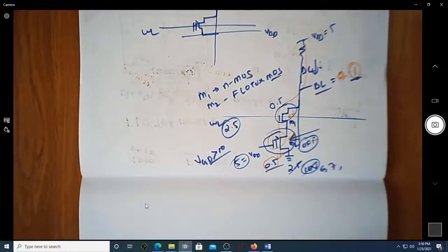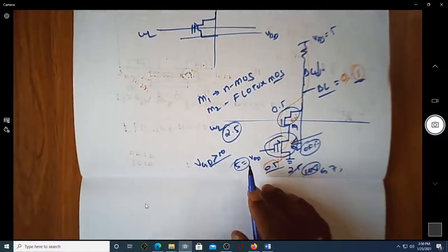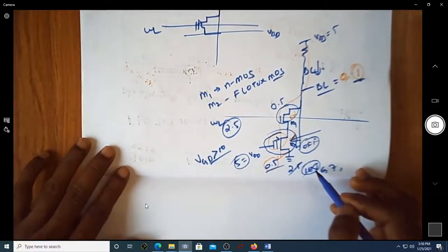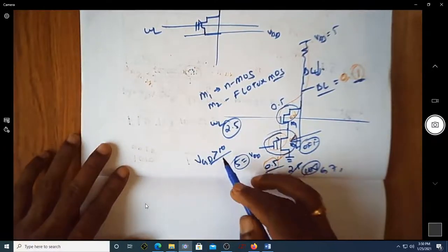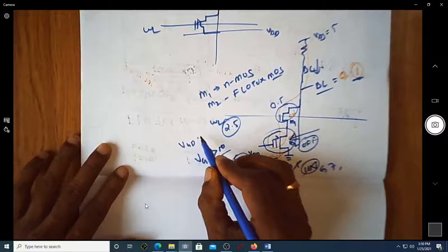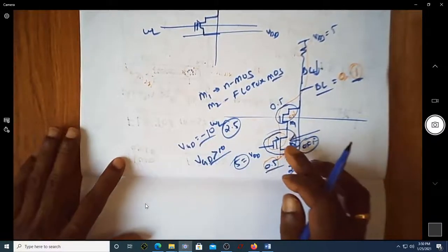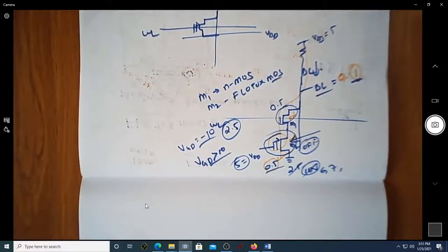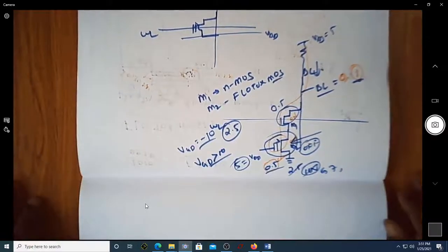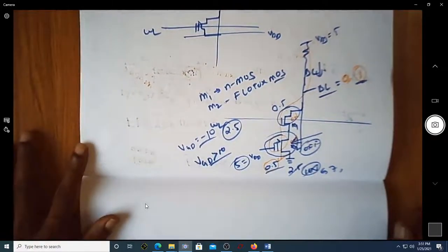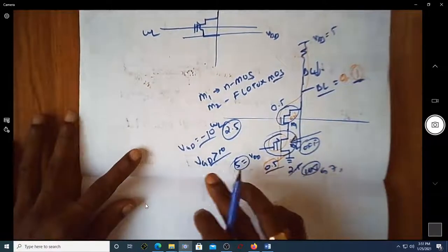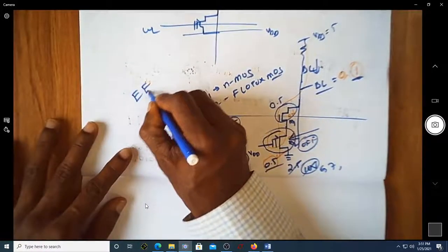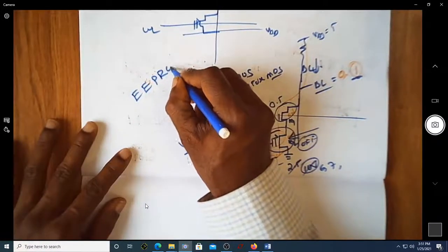This is one of the major advantages. Supposing that you have increased the threshold voltage of this to 10 volt, if you want to bring it back to a lesser voltage, you can apply VGD equal to negative 10 volt, then whatever charge was stored there will be restored. It will have a reduced threshold voltage. Since we can program it to either a lesser or a larger threshold voltage using the electrical voltage between the gate and source, it is called electrically erasable programmable read-only memory.